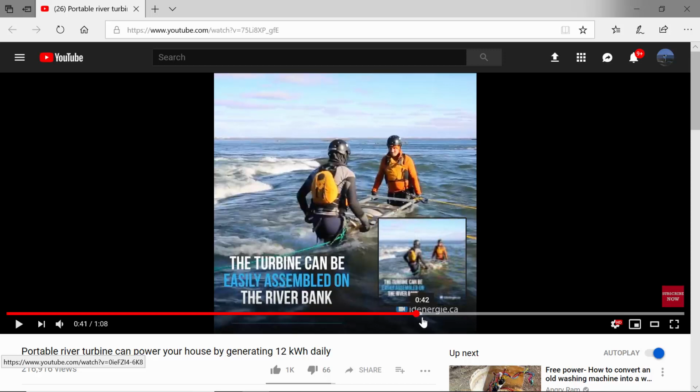So it wouldn't be very good like in the Mud River. You know, those slow-moving, quiescent streams that don't have very much velocity head, you're not going to be able to generate much electricity. It also wouldn't be very worthwhile in a reservoir in a small watershed. If you only have 20 or 30 acres upstream of this thing, then there would only be water going through the channel in the immediate aftermath of a rainfall event. So we're kind of picking where this would be best suited.